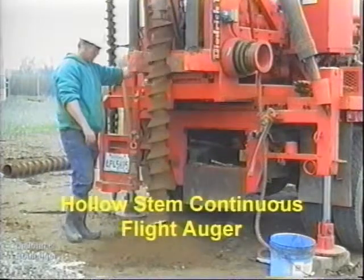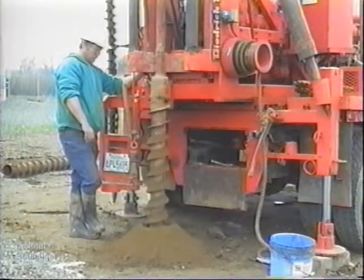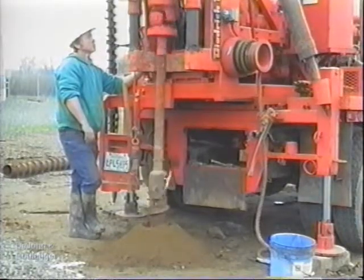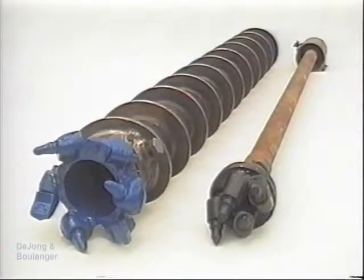Hollow stem continuous flight auger drilling is similar to the solid stem method in that the hole is advanced and soil is removed by the flights on the augers. The primary difference, as seen on the right, is that the auger flights are hollow. This allows a sample to be taken by lowering a sampler down through the hollow stem, thus eliminating the need to remove the auger from the borehole. The basic hollow stem setup is shown here.